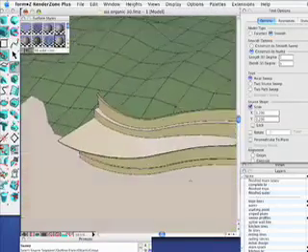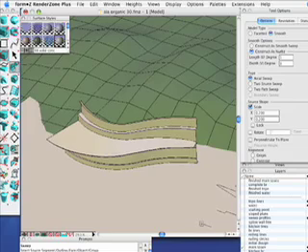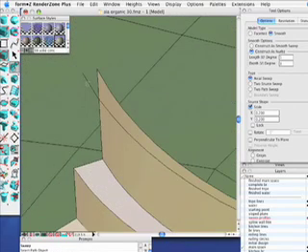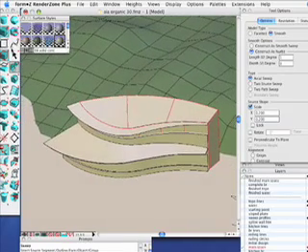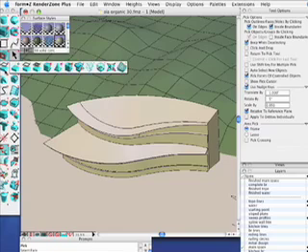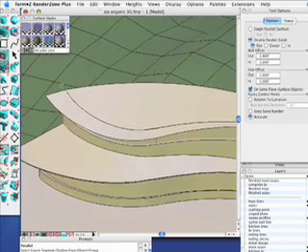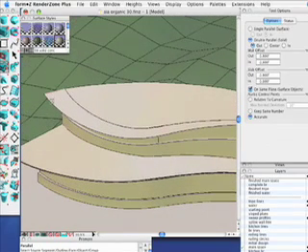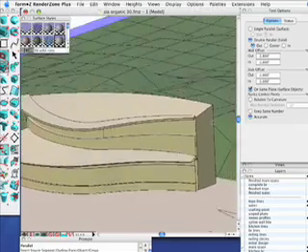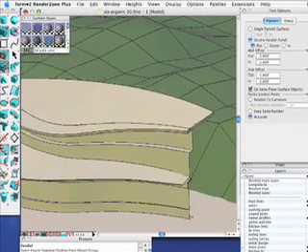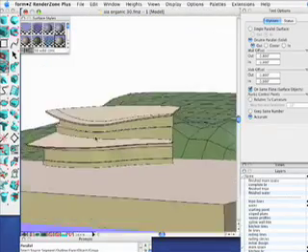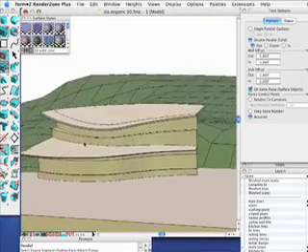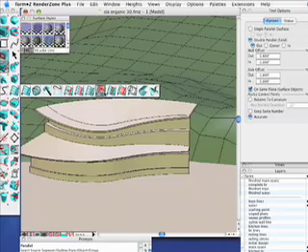I'll do the same thing for this last overhang, another axial sweep. So I'll select that object and the line it's to go on. I'll bring my original object back on and let me do a parallel offset of these top faces to get some surface thickness there. I'll just pick this face and the face of my original object. So you can see I very quickly generated a pretty organic form from my original block.